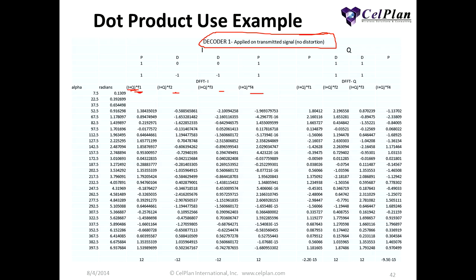And in the end, as you can see, I get a number that is plus or minus, but where I didn't use the subcarrier, what do I get? I get 0. So it was able to decode, through the dot product, through the orthogonality property, the signal I sent. You can see that 12 corresponds to 1 and minus 12 corresponds to minus 1. So basically this is the principle of OFDM.